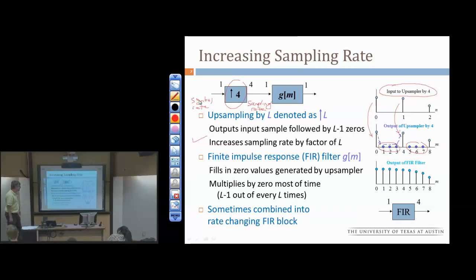All right, to clean up these artificially high frequencies introduced by inserting these zeros, we'll filter. Not a surprise. And this filtering will connect the dots. It depends on how it's designed, but it certainly will connect the dots. And if it's designed right, we don't change at all the original samples that came through on the input to the upsampler. So if we choose the pulse shape or the impulse response correctly, we don't at all change what we started with. But instead, we fill in values between those values that we know.